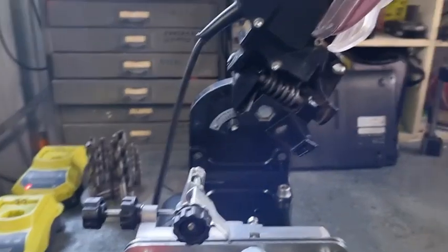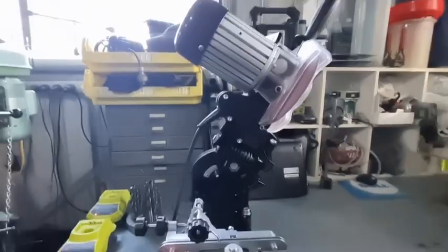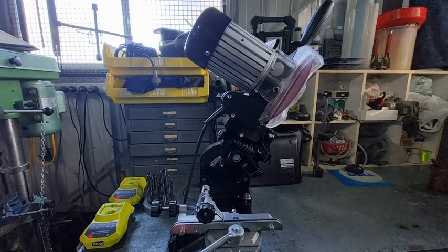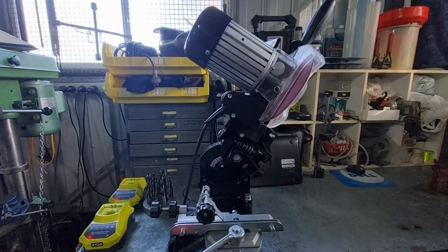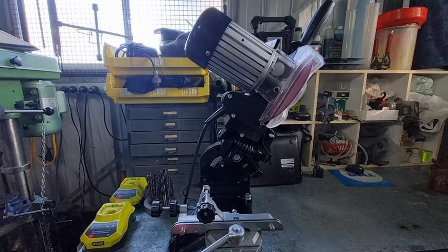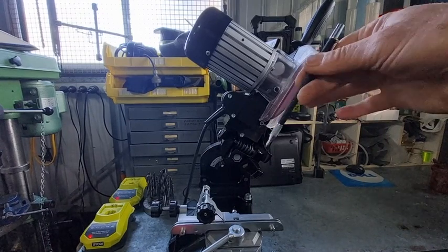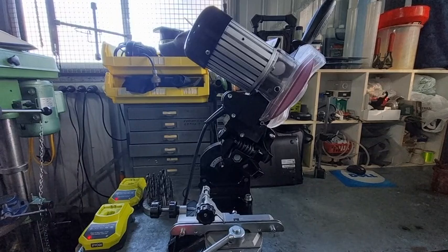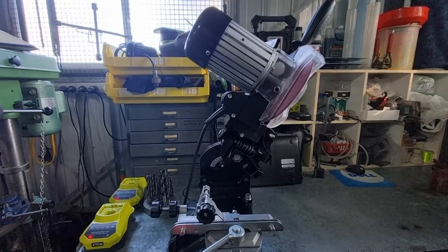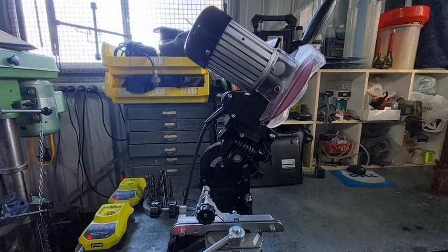The top plate cutting angle, which is the angle of this grinding wheel here, which on this grinder is set at 60 degrees. You can set it at 55 degrees or 50 degrees. If you set it at 50 degrees, it leans over a little bit more, so it's a little bit more aggressive. And again, the more aggressive you go, the quicker it blunts. So typical 60 degrees is your best all-rounder. Okay, so that's the Oregon.